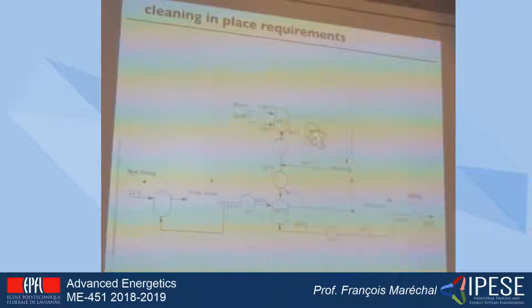Now, this water is going to exchange heat, and in fact also take dirt here. It is exchanging heat with the bottles, and therefore it is going to decrease the temperature of the water from 85 to 65. And you need to recycle it, so it means that you need to reheat it from 65 to 85 in this loop. So it means that at the end, I need 1, 2, and 3 heat exchangers with 3 cold streams.